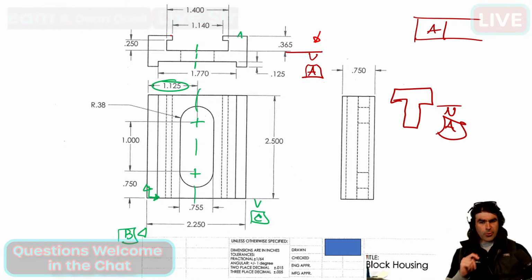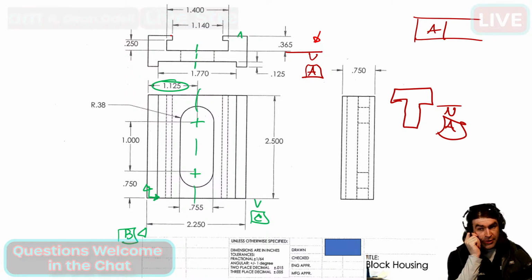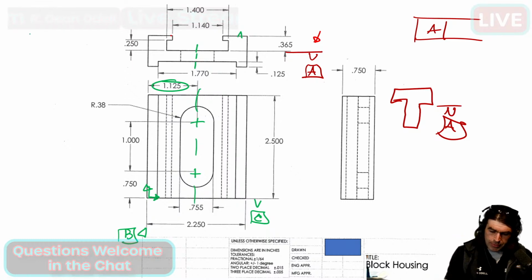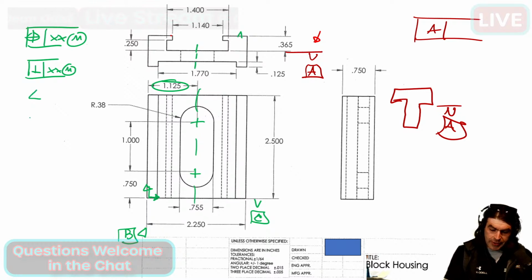Okay, I got a question real quick. Which geometric tolerances can use the MMC modifier? The answer is anything controlling. Okay, so let me write it. So position can use MMC, perpendicularity, right? Angularity, parallelism. I won't write out those full feature control frames.